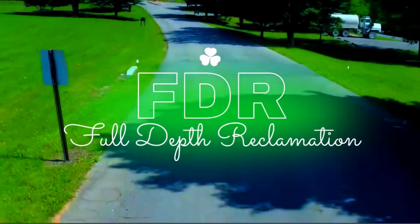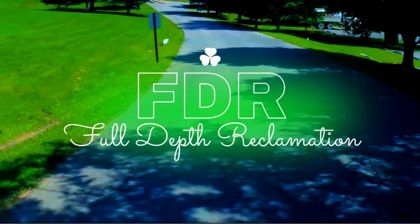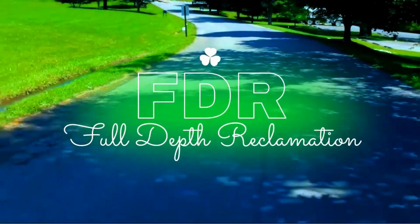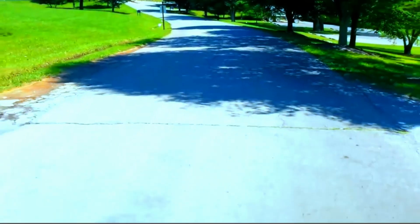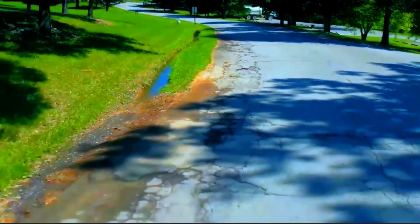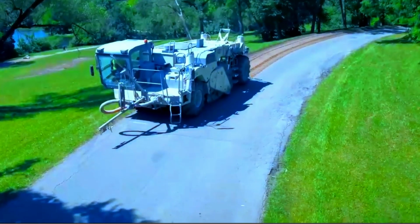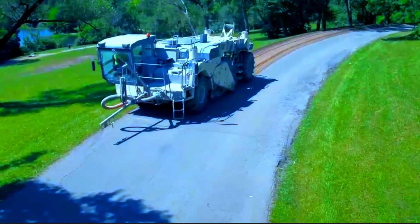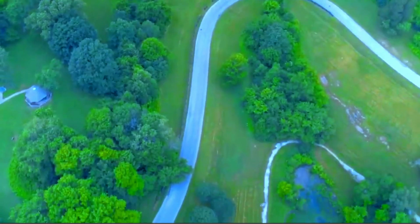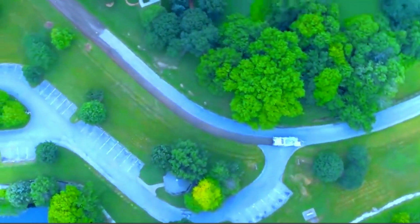Full depth reclamation, FDR. When the base is unstable and the road's foundation is weak, then full depth reclamation, FDR, is done before laying asphalt. It is a sustainable technique where the entire existing pavement, including the asphalt and base layers, is milled, mixed, and stabilized on site to create a solid foundation. Instead of hauling away old materials, everything is reused, making this method both cost-effective and environmentally friendly.